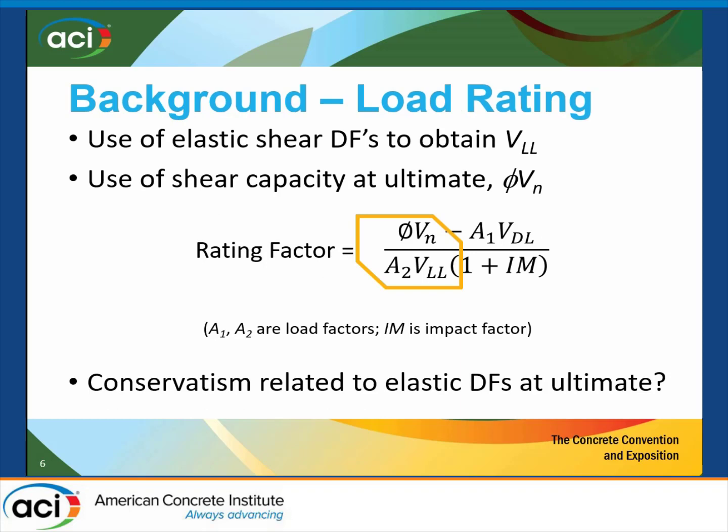Load rating is thinking about a few things, and there's a very general equation here with a few important things in that yellow shape. The first one is that I previously mentioned these distribution factors, which are equation-based in the United States and come from elastic behavior, elastic modeling. That's how you get your truck load into an applied live load shear. So if you wanted to rate for shear, the applied load is the live load. That V sub LL, for live load, comes from an equation that's elastic. And that's on the bottom of my rating factor equation.